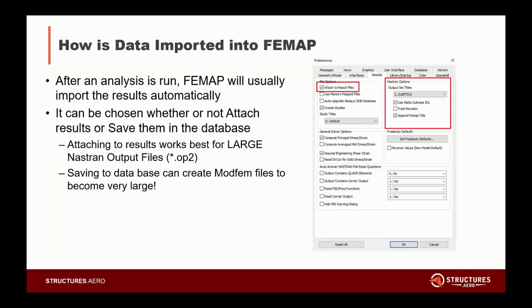As you can see on the right here, I have boxed out "attached to results." There are two ways that you can import the data. It'll either get saved into the ModFem, or you can just have the ModFem reference your OP2 files. When you have OP2 files that become very large, it's more beneficial to have them attached to the results, because otherwise everything gets saved to the database and your ModFem files will become very, very large.